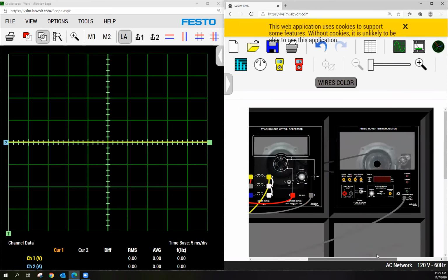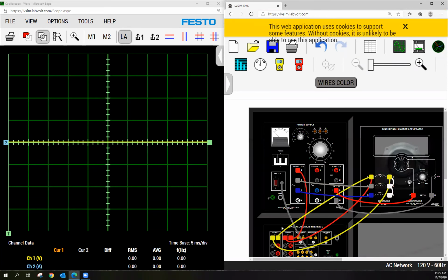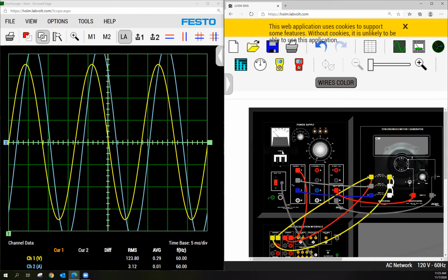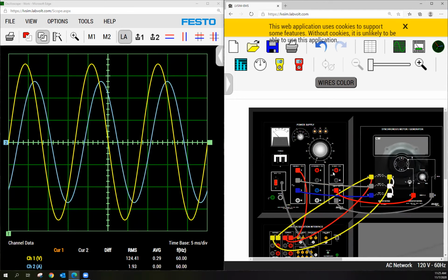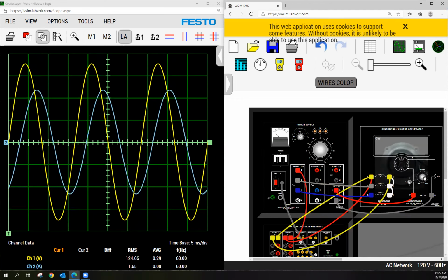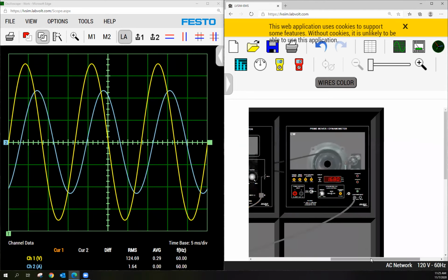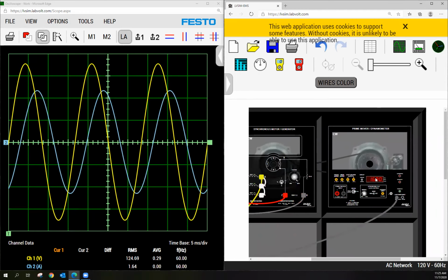We have it connected to a dynamometer here, so we can measure the torque and speed. Let's just start this guy up and see what we get. I'm going to power this up, and when I hit it with that 3-phase voltage, the field current is actually off. Notice I have this off switch. And notice I'm spinning up, and it spins up at 1680.